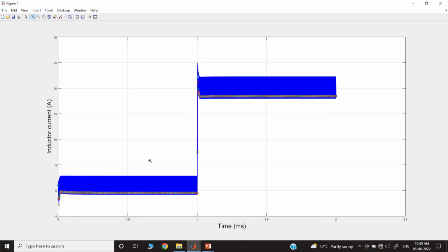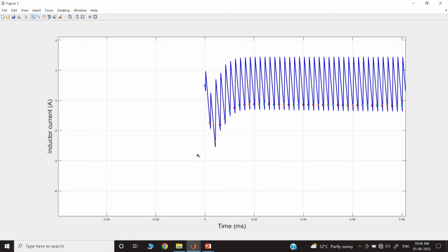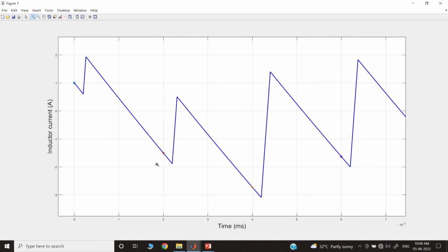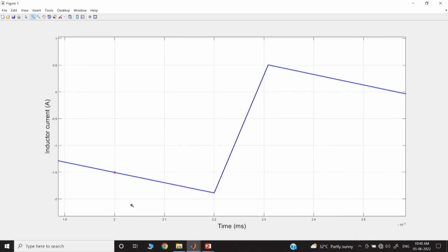We have discussed that if you consider interval 2 sampling with a Ts amount of delay, so it is delayed, and this delay amount we have set to 200 nanoseconds. Sorry, our time period is 2 microseconds, so divided by 10, it is 0.2 microsecond, that means 200 nanoseconds.